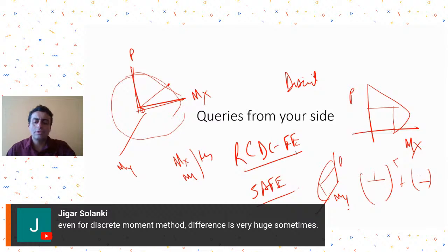So what I would say is that wherever you are getting a mismatch in the ETABS and RCDC results, you first try to match the interaction curves. ETABS also generates interaction curves. RCDC is also able to give you the interaction curves. So you match those. If those interaction curves are matching, then it should give similar results. If the interaction curve is not matching, then you need to look into the reason for mismatch. Okay, clear? Yeah. Very good. Any other question that anyone has?